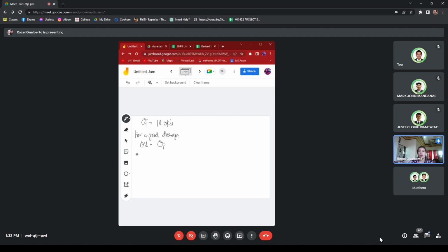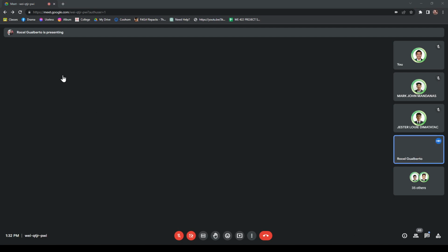Based on the ultimate strength, this would be sigma u over factor of safety equal to your flexural. Sigma u, as stated earlier, we did not change the material, so this is 102 ksi divided by factor of safety, equated to the new flexural stress, 10.8 ksi.